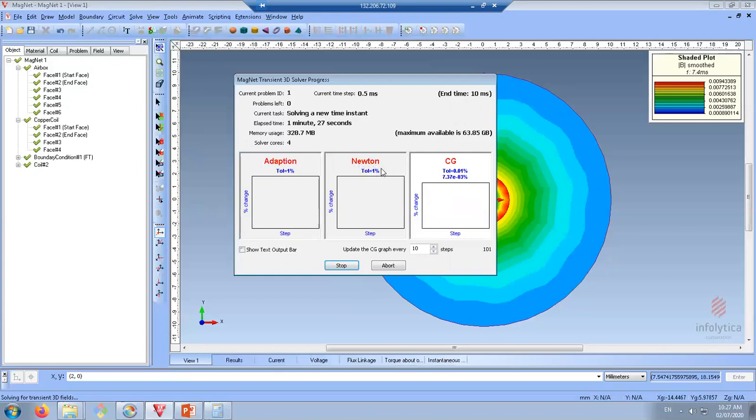If you increase the tolerance, obviously it will solve in a smaller number of steps. However, the results wouldn't be reliable enough. Let's see what else we can do to change the speed of the process. So one of them is mesh density, the solver.